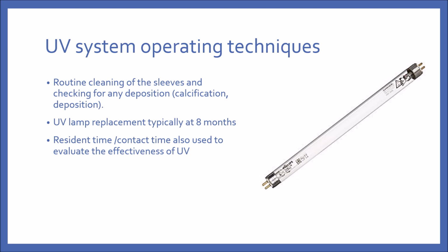Residence time, the speed of fluid flowing through the reactor, is also important. Increasing velocity or increasing flow rate through the reactor would mean a shorter contact time, meaning that the pathogen will not be effectively destroyed.